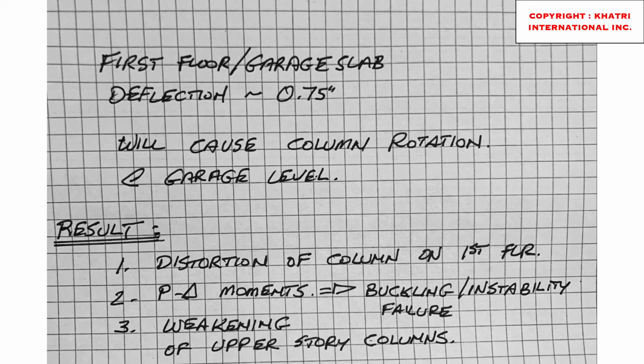We do need to look at this on other existing buildings, because this is a point of failure that can be measured. This is a root cause that can be measured in the field, and we can document it, and we can potentially predict a collapse before it occurs. Because if a building is sinking non-uniformly and the caps are rotating, we can measure that using instrumentation, and then we can tell our clients whether or not their building is shifting.